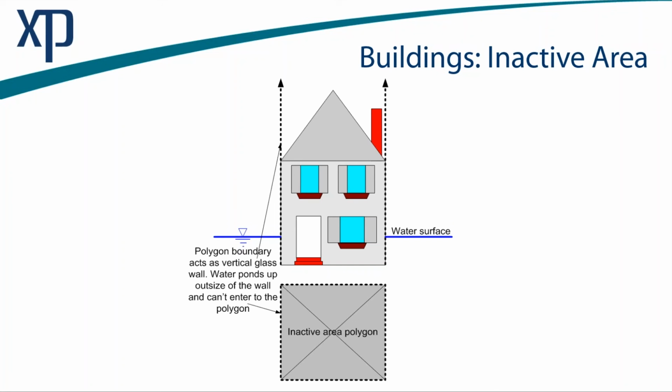And it's a great way to represent, I think, fast-moving flood events where you're not going to have a lot of inflow into a building, or you're unlikely to, or at least modeling that would be more effort than it's worth. It's a great representation of how the flow is going to act between two buildings, and in a fast-moving event, it's a very valid way. But it's totally up to your engineering judgment. Each of us, when we're modeling, has to take into account all of the components of the model and make the decision on what treatment to use.